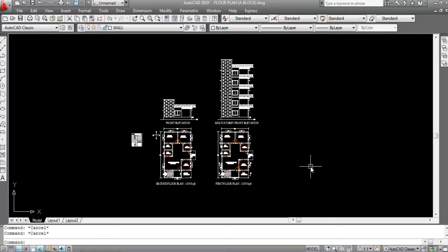Okay. So, a building section shows a view along an imaginary line cut through the building, indicating structural and construction elements. The position of section lines are drawn and located by letters A, B, etc. on the plan of building. At the ends, the lines are marked by arrows to indicate which part is to be seen.